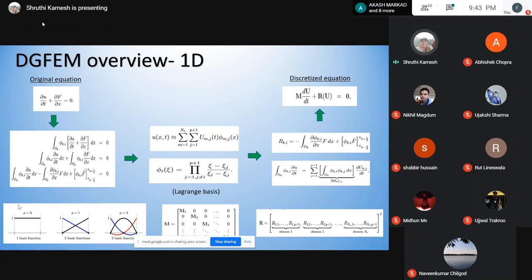This is a volume term, but it's not as strict as the first volume term. And the first volume term is what is used for time stepping, which is that if we do not resolve this, you will not know accurately how the solution varies in time. The second term over here is more for spatial variation in the volume, right?